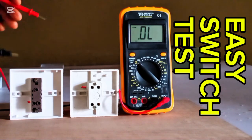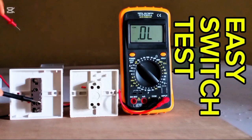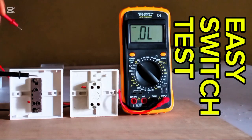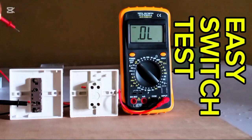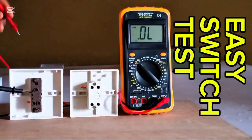So this is how to test this two-way switch. The condition of this two-way switch now is good, but if internally they are shorted, both will read to common. Line 1 and 2 will read to common in each flip, and so it makes it bad. And if common to either line 1 or line 2 that is meant to read fails to read, it means it's open. Therefore, the switch will not be suitable for use.